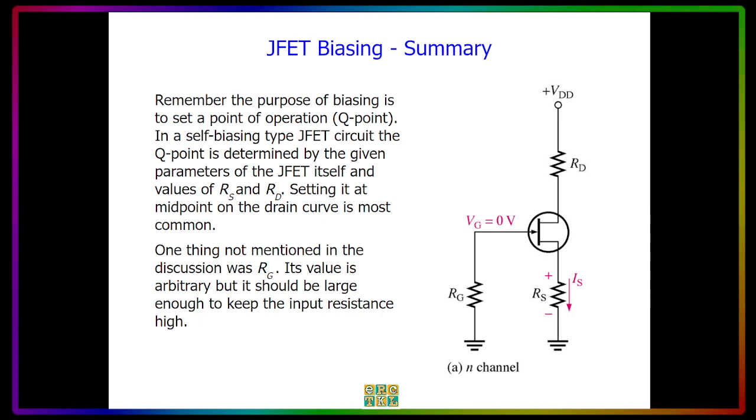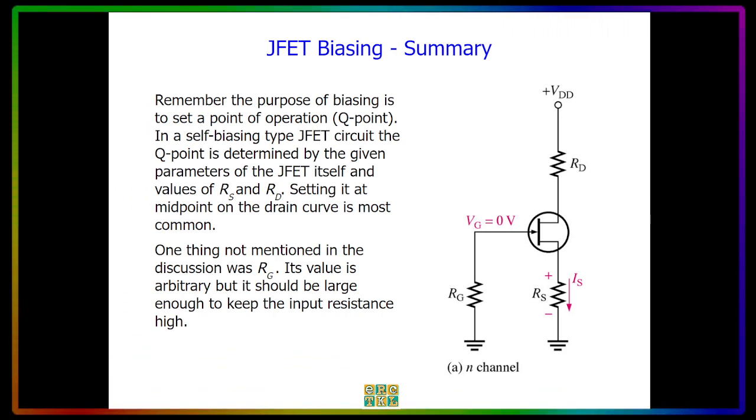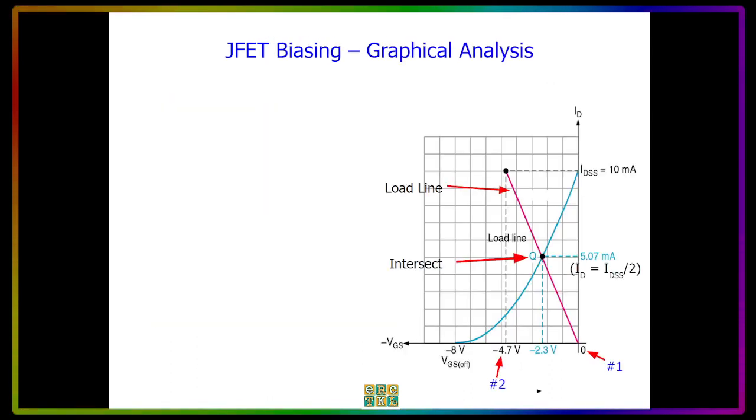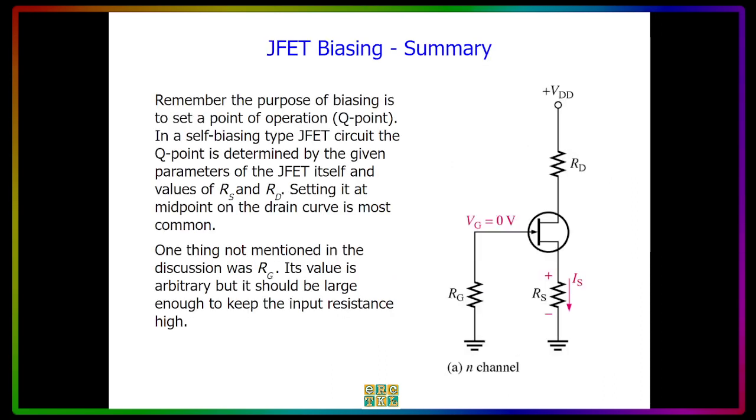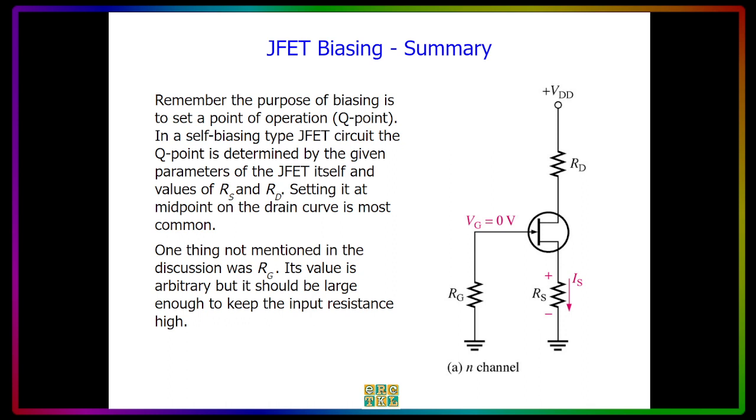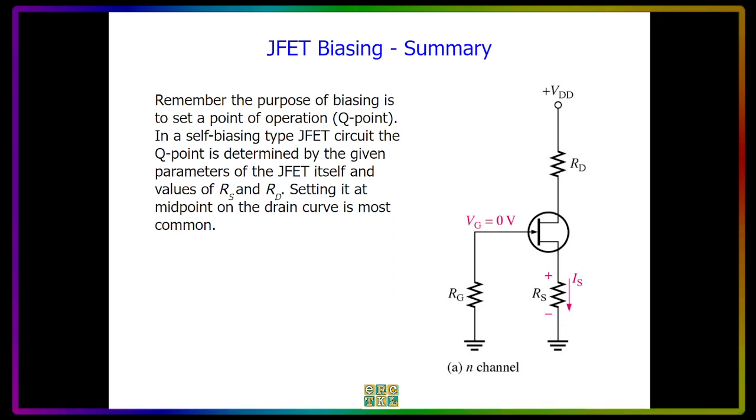And one thing not mentioned in the discussion was RG. Its value is arbitrary, but it should be large enough to keep the input resistance high. So you can use any values for RG, but make sure that it's large enough to make the input resistance still high.